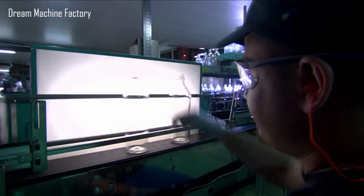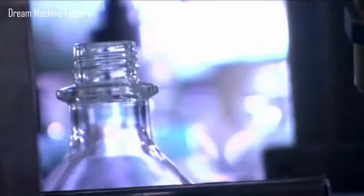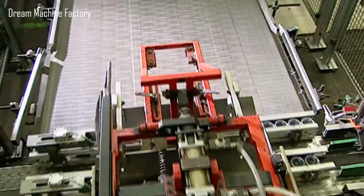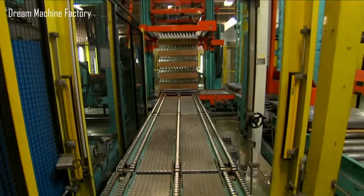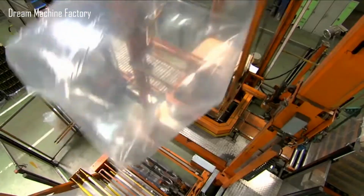Quality control is rigorous. Sensors and probes check sealing surfaces, dimensions, wall thickness, and detect imperfections. Any defective containers are removed from the line, crushed into cullet, and fed back into production. Finished bottles and jars are packed onto pallets using reusable or recycled materials, then wrapped for protection during storage and transport. They are shipped either directly to customers or to decoration facilities for branding.